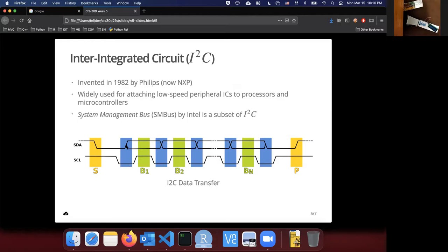At this time, when we're getting ready, the clock is at a low voltage. Then on the next pulse, the clock is pulled up into a high voltage, and the data line maintains that signal. During this stable phase of the clock signal, we read the data, either 1 or 0. Then the clock goes down again into low voltage so that the data line gets ready for sending the next bit, which can be 0 or 1 again. This same process goes on and on, and it will send all n bits.